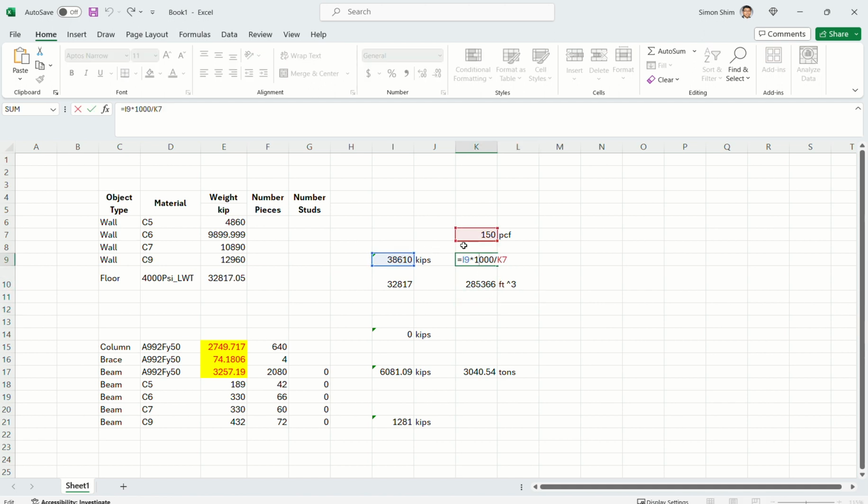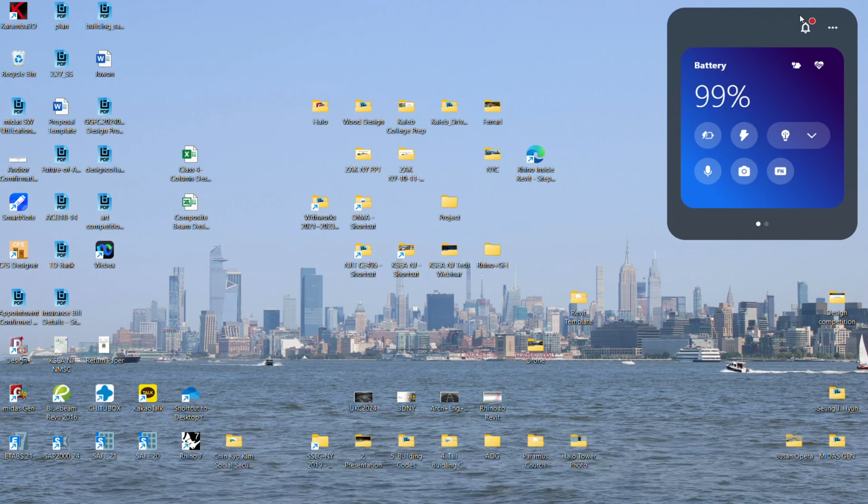So this is slab total concrete volume. This is just only wall. This is still tonnage. So basically concrete wall and beams, you can sum them up and divide by 150 because they're normal weight concrete. Floor slab, we assume they're lightweight concrete, so you need to use total weight divided by 115 so that you can calculate this. So that's how you can use the material takeoff.